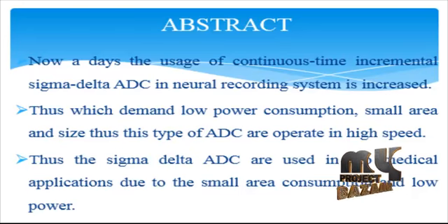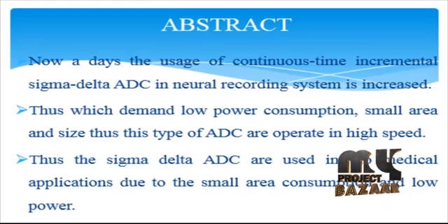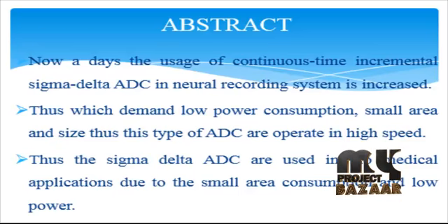By employing a high-resolution ADC, this requirement can be much relaxed, and several power-hungry signal conditioning blocks, for example the additional gain stage and the active anti-aliasing filter, can be simplified or eliminated. In this paper, we take a step further, proposing a more power-efficient sigma delta alternative for high-resolution multi-channel data conversion. The proposed design combines the speed of the pipelined ADC and the resolution of the sigma delta ADC, so high resolution can be achieved with high density of ADC based processing.